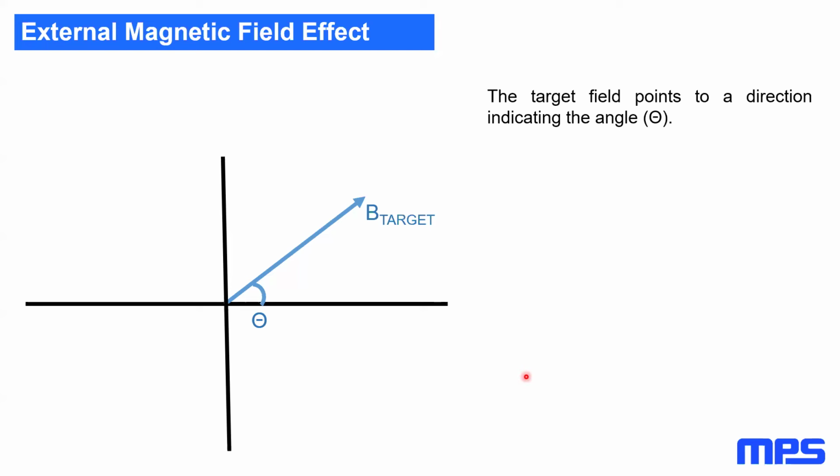If I've got zero current flowing through the current sensor, my output should be zero. But if I've got an external field that's now causing the Hall sensor to give an output, my sensor may say, oh no, I've got 3 amps, 4 amps coming out of the sensor, and that is a 4 amp error. There's in fact 0 amps going into the sensor.